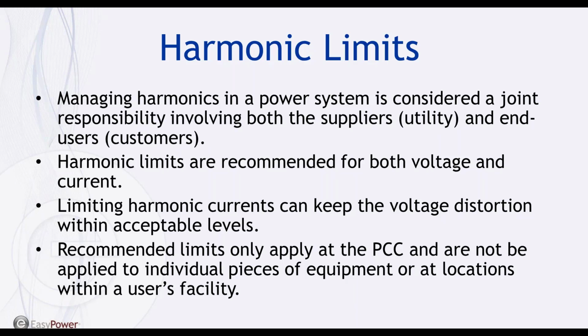IEEE 519 also states that the recommended limits only apply at the point of common coupling and are not to be applied to individual pieces of equipment or at locations within a user's facility. In most instances, the harmonic voltages and currents at these locations can be found to be significantly greater than the limits at the point of common coupling due to the lack of cancellation or other phenomena that tend to reduce the combined effects of multiple harmonic sources.